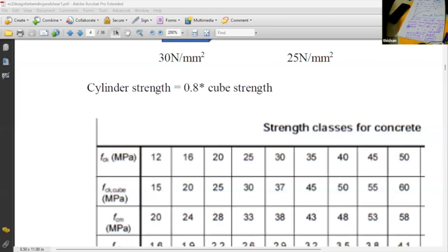And vehicles also drop various chemicals, and they might even be in the coastal zone, where there may be chloride attacks. So all those can be very well controlled if you are using 15% fly ash in pre-stressed concrete members. So the reason for using fly ash in pre-stressed concrete is actually that it's detrimental to early strength, but if you are interested in reducing the chloride attack, then using 15% fly ash is highly recommended. So for each thing, there is a different reason.